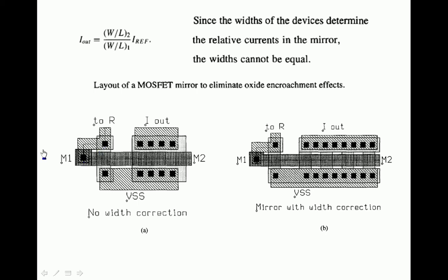So this is a simple current mirror without width correction. That is, we have taken the M2 transistor as a single transistor, whose width is 4 times that of the M1 transistor. Now this is with width correction. If you observe cleanly, you will find different lines. These lines imply this is the M1 transistor, and a replica of M1 has been used 4 times.